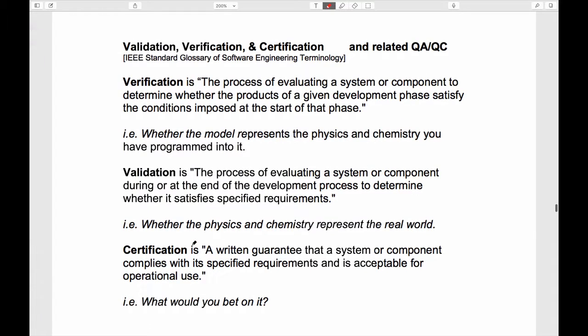It doesn't mean that you need to develop your own codes, but for any code that you pick up off the shelf and start using, verification is something you should do, just to prove to yourself in a simple way, exercising it in as many ways as you think prudent, that it's really doing what it's supposed to do. It may well be that it's doing what it's doing, but you've interpreted one of the instructions for a material property in the wrong way.